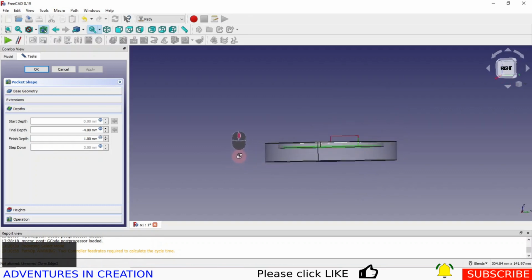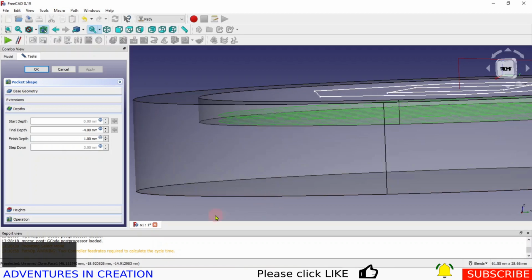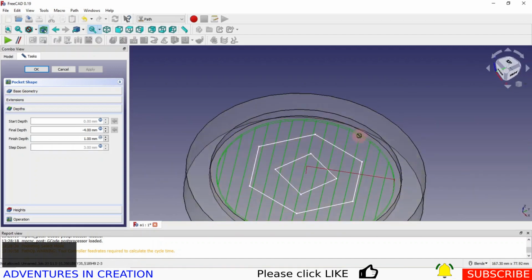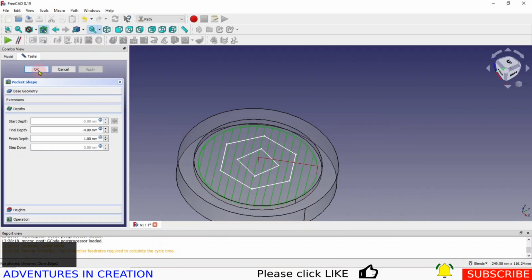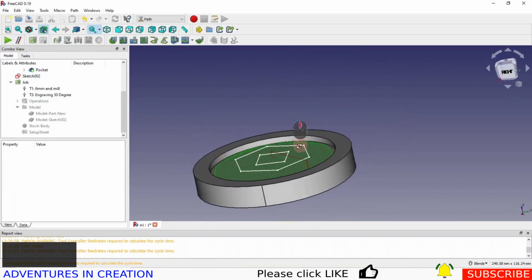So we do have 2 layers there. If I zoom in, maybe you can see them a bit better. The green layers, there's 1 there and 1 there. So those are my 2 cuts. So everything looks the way I would expect it to be, is going around the outside. Now remember, this is the center of the cutter, so it's actually going to cut out to that edge. And we'll say okay to that. And that's our first part of the job done.